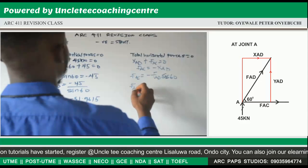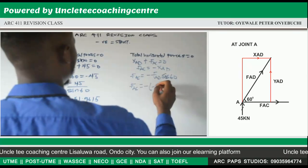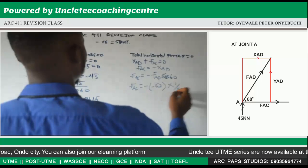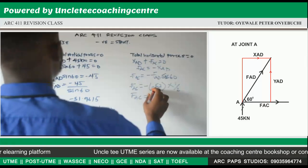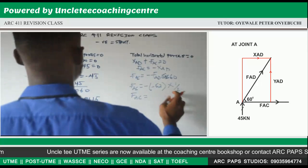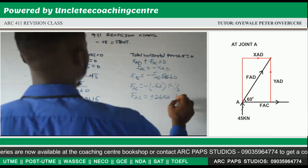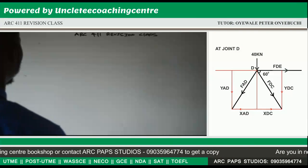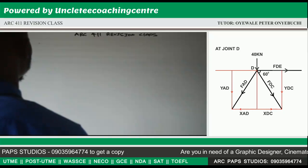Now our FAC will then give us minus 52 kilonewton times cos 60, which is 1 over 2. Our FAC will then give us minus and minus, that is plus 52 divided by 2. That will give us plus 26 kilonewton, which is a tie. Now we have finished resolving joint A. Now we have to resolve joint D, going to the next joint.